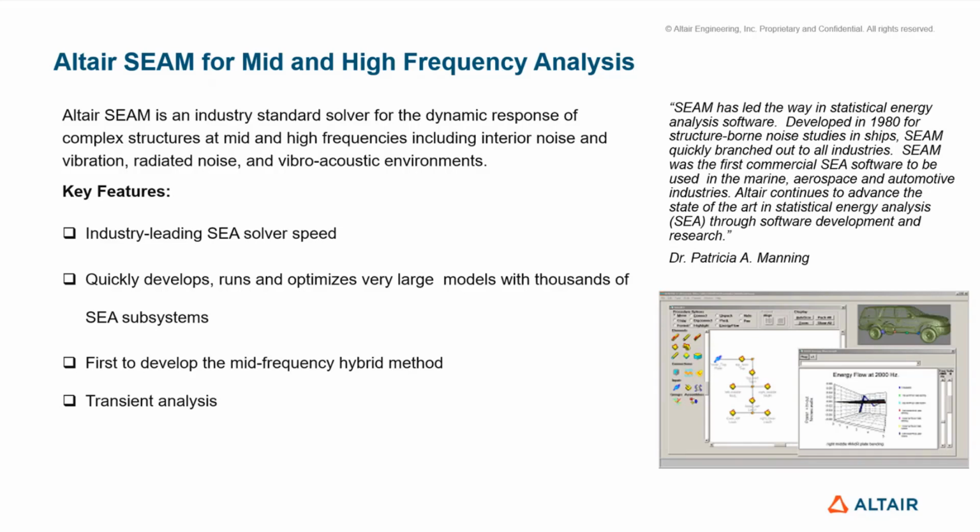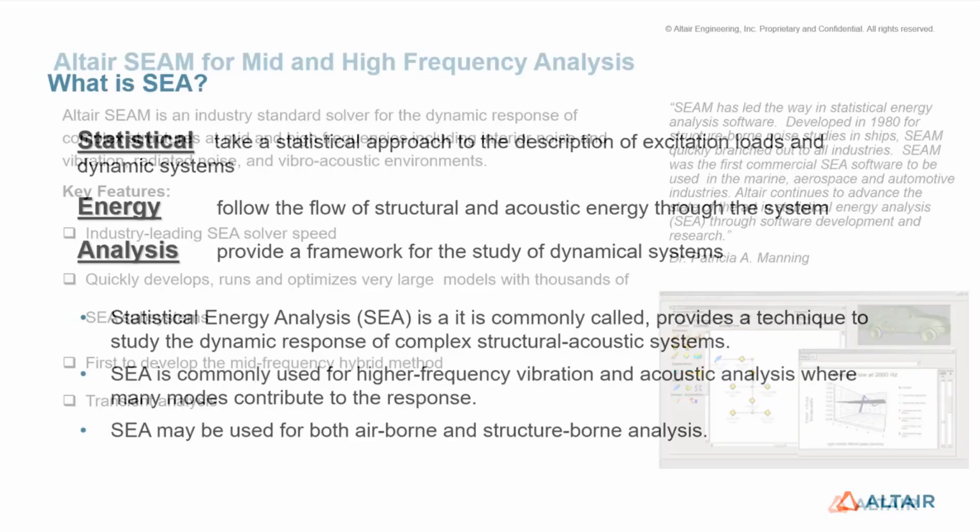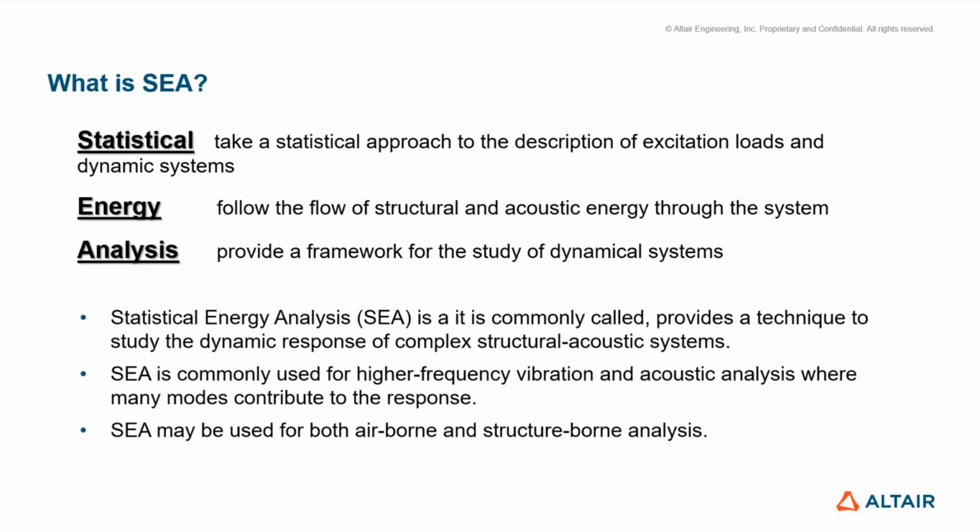As I explained, SEAM uses a statistical energy analysis solver behind the scenes, in which rather than the finite element method, we use an energy method to solve the equations. From the energy, we derive the displacements or pressures which are required for dynamic analysis, rather than FE, where we solve for displacements and then get energy and stress and strain. So here it is kind of reverse, and it uses a statistical approach to do it. The reason I'll explain further.